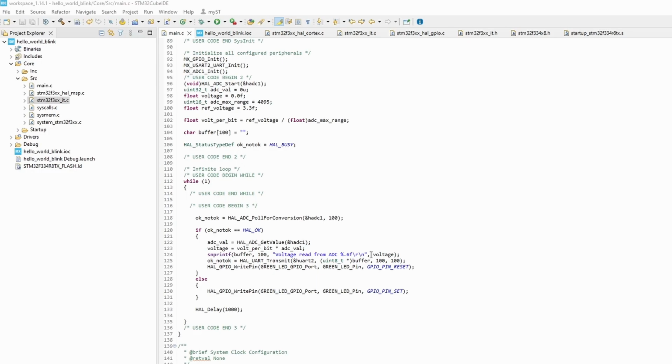Now interrupts are really important because whenever you're developing a low powered embedded device, you don't want the device on all the time and you don't want it sampling all the time. So what tends to happen is you're reading a sensor, and the sensor's set up to read and it'll continue sampling and storing the data, and eventually all that data will be ready to process because your sensor will have run out of space. So what tends to happen is the sensor can ping the microcontroller and let it know that data is ready, and it does this using a thing called interrupts.